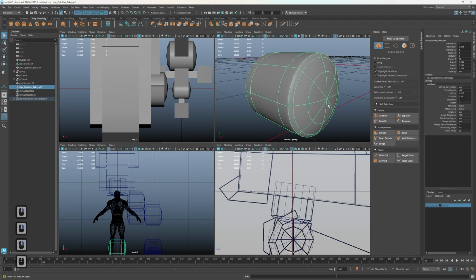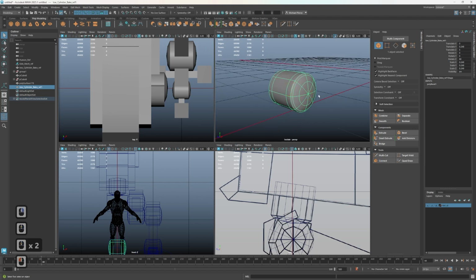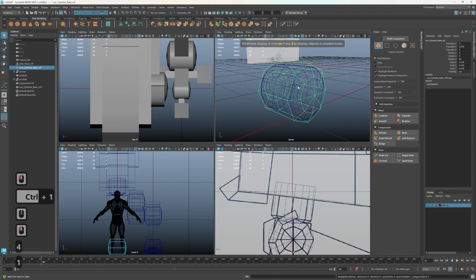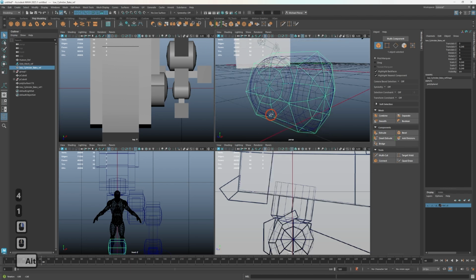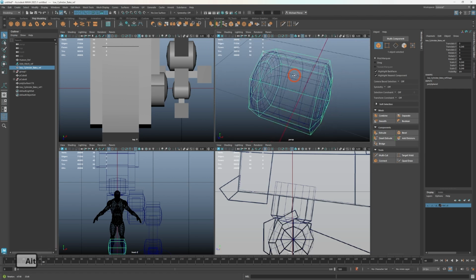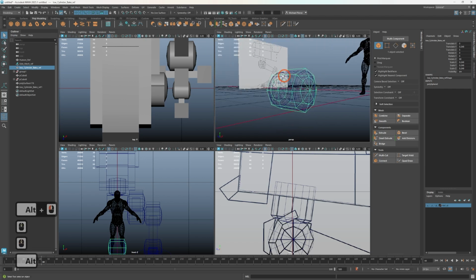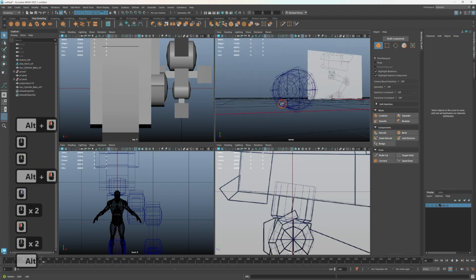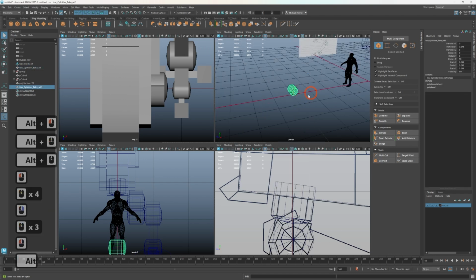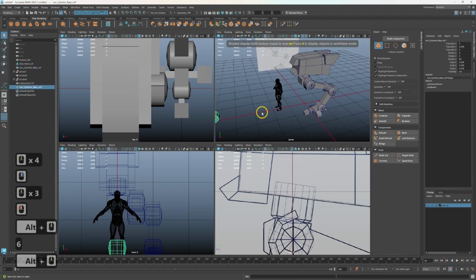So subdividing will basically turn one polygon into 4, in which case for our high poly we are going to smooth this, right? And then if I hit wireframe, you can already kind of see what's going to happen here in the wireframe, right? How these things don't match up. So you're going to have these little artifacts here because it doesn't quite hug the mesh when we actually bake it down. Which is why I'm going with you can start with even higher and then take away edges as you need it, as long as you don't destroy the UVs when we make them.